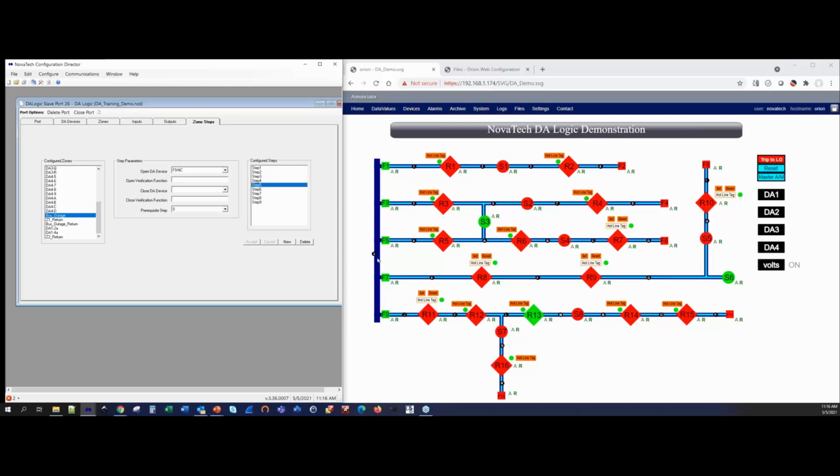That will separate the outage bus from the feeder, and then it will start looking at when the open step is confirmed as being complete. So it's going to communicate to F1, verify that it's open, then it will move down to the close step, and it will close switch 1. And it will do that based only on the actions and the state of feeder F1. And it will execute that. At that point, feeder F1 is bridged to feeder F2, and that feeder is restored.